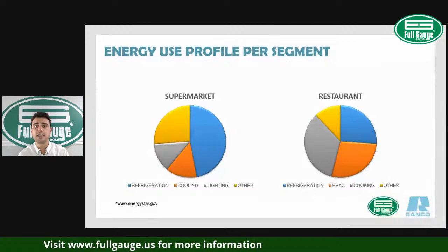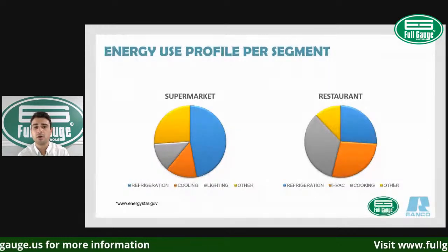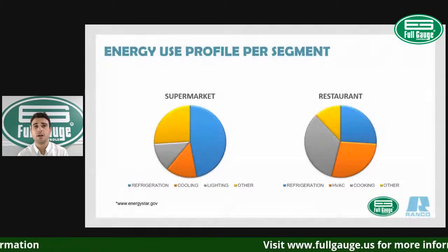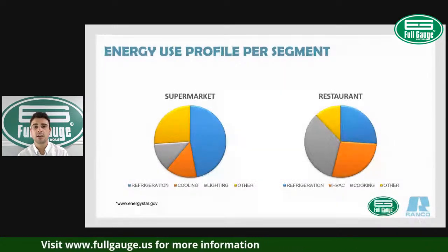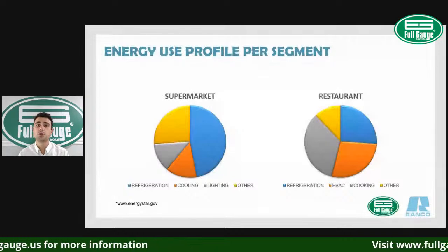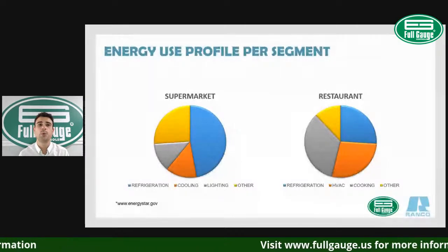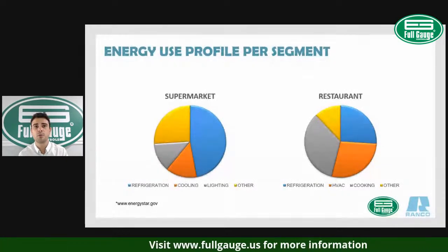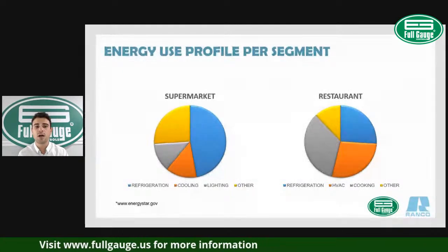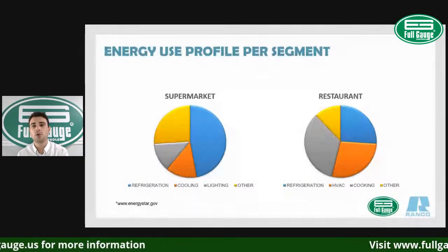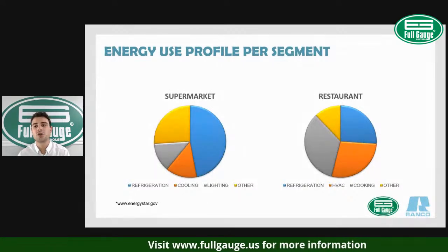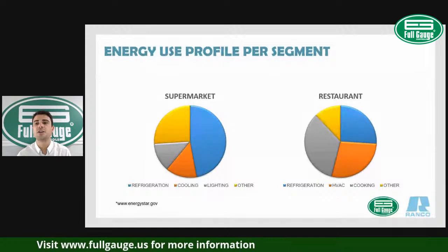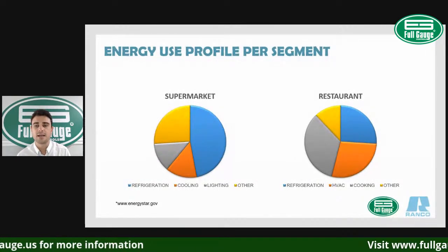So food safety is the first selling point, Michael, that you can bring to your customer. In addition to that, energy savings. You can save up to 20% energy just by switching from a mechanical thermostat with a time defrost to an electronic controller that will control that process based on a microprocessor and have energy efficient defrost within it.